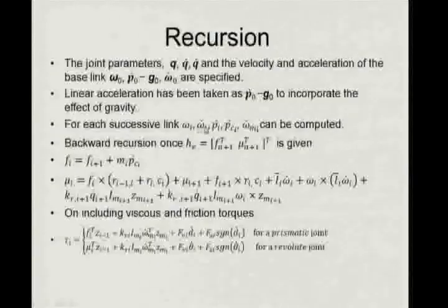So once you do that, first you go calculating the angular velocity of each link, the angular acceleration of every link, then the angular velocity of the origin of coordinate system I, angular acceleration of the center of mass, and then the angular velocity of the motor shaft. So this we have already seen the formulas, and then successively you just keep doing kinematics and you compute them.